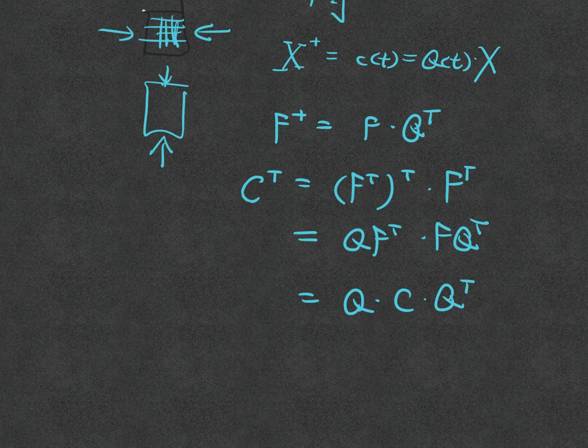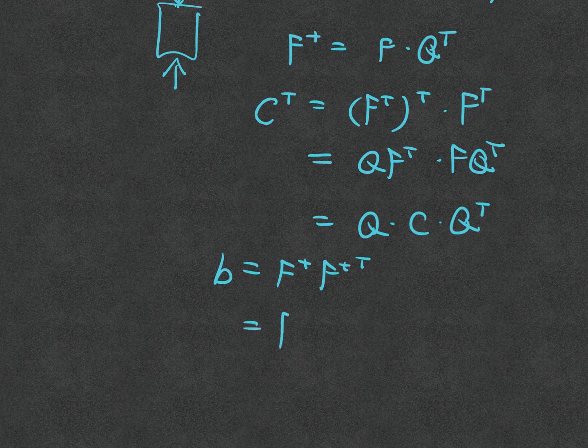So you see here the Q no longer gets cancelled out. Instead we get something like a stress-like equivariance. You see what I mean? Do you see that? Now what happens to the B matrix? The B matrix, on the other hand, because it's defined like this, is equal to F Q^T Q F^T, which equals F·F^T, which equals B.